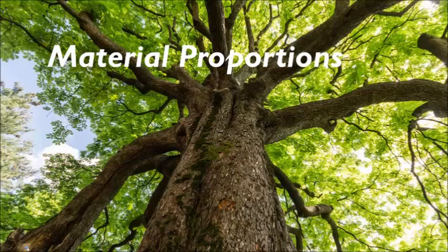So if I have, for example, a 2x4, then that 2x4 is only going to be able to span a certain distance lengthwise before it starts to either sag in the middle or before it starts to fail or break or crack or show some signs of weakness. And if that's the case and we still have a need for using that particular material in a particular application, then we would need to increase its material dimensions, or its proportions would need to increase.